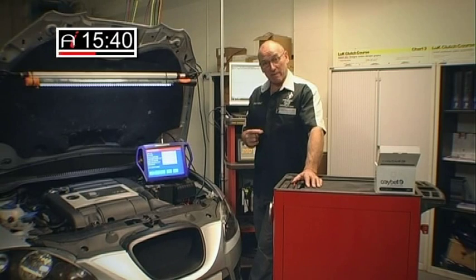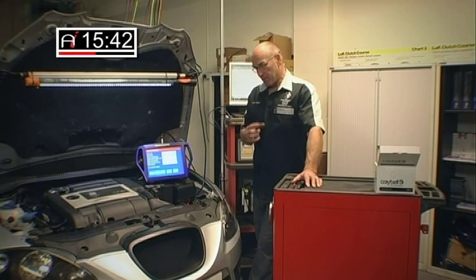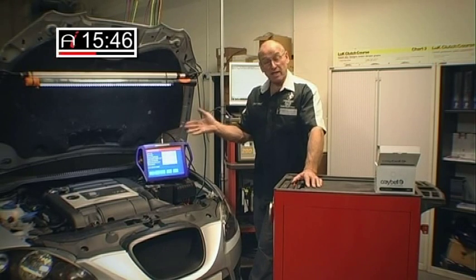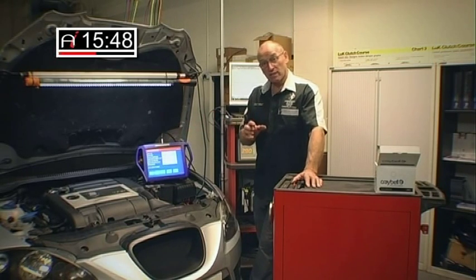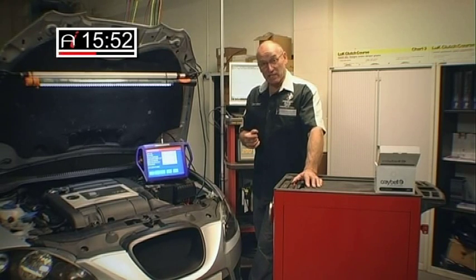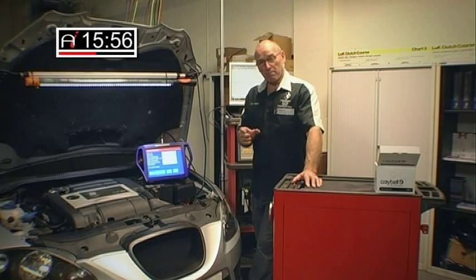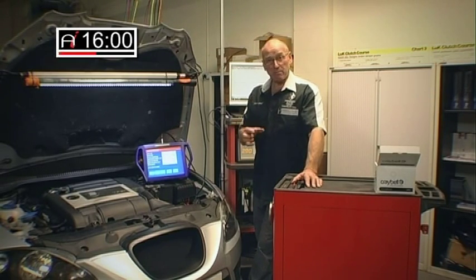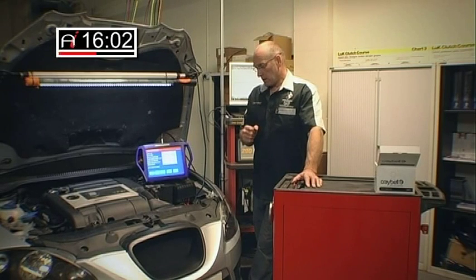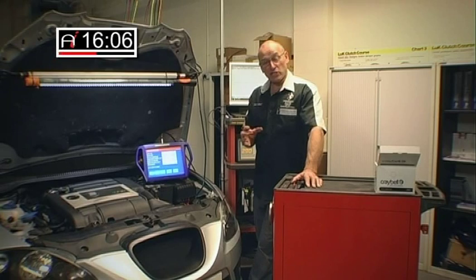When digital air mass meters came out, that presented a problem: the frequency of the air mass meter, which in our case will vary from around 800 Hertz, Hertz being 1 event per second, to about 9,600 on full load, could not be displayed on an oscilloscope with things like lambda and APP. So it took us a while to resolve this issue. It's been resolved in two ways.